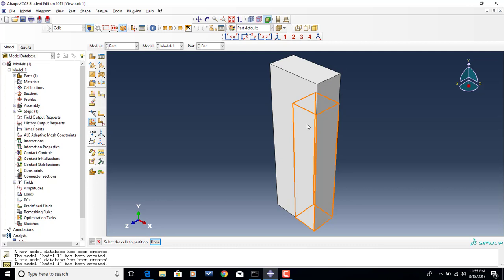Something I would like to do further, just to help me from a meshing standpoint, is this: if I go to try to mesh this aluminum portion, the outer portion, as it goes to wrap around the corner, this could cause some difficulty. So to make things easier, I'm going to continue this partition straight across, and that will make the meshing a little bit easier. I just need to remember when I assign properties that it's only this core region here that's going to be different.